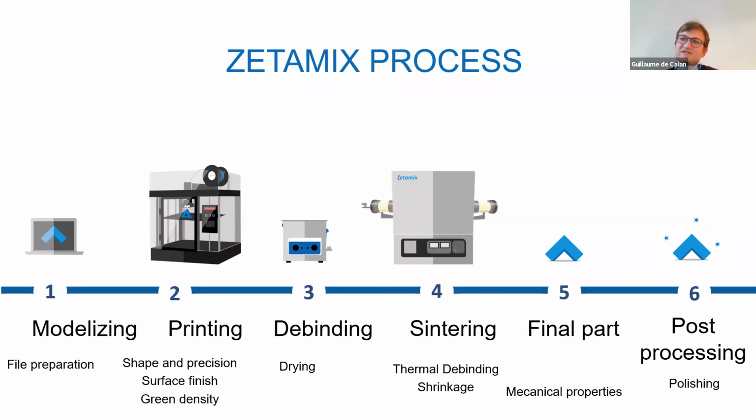Are the technical materials compatible with the use of soluble support materials? Yes, we've been using a bit of soluble materials. You can even use any thermoplastic, even if it's not soluble, because with the post-process you're going to remove it without having to remove it by hand. If you heat up, it's basically going to melt at some point. So yes, we've done it a lot with PLA actually, and we just heat it up to melt it away.